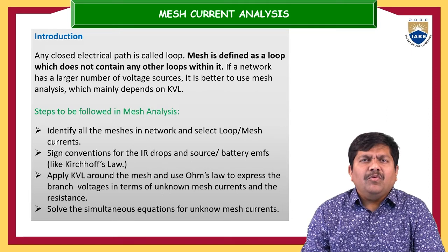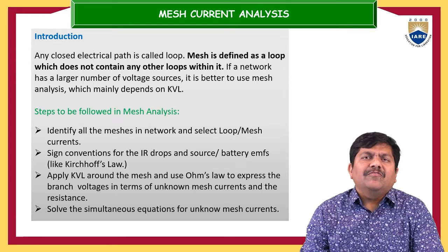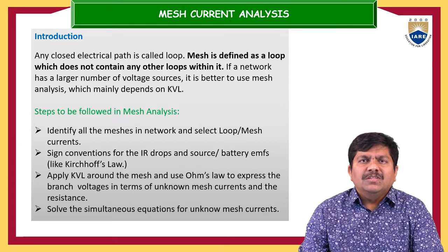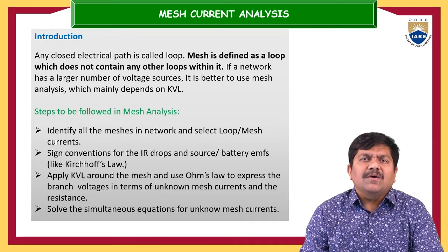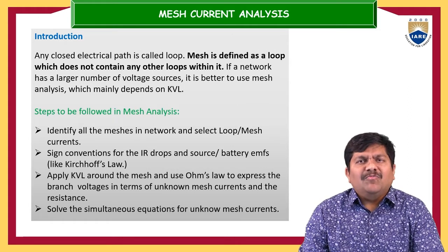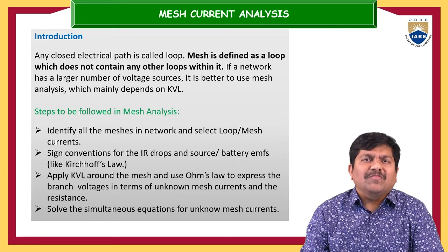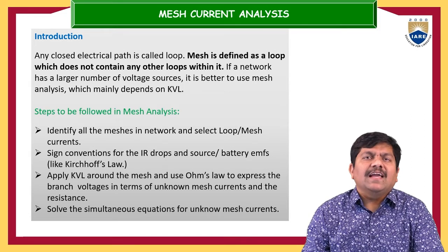Before moving into the circuit analysis, by seeing the circuit itself we should get some idea of which technique is more apt to analyze the behavior of the voltage sources or current sources in the connected system. The thumb rule is: more voltage sources, mesh analysis; more current sources, nodal analysis; a combination of the two, source transformation. Source transformation will not give the complete analysis, but it is highly helpful to simplify the network.